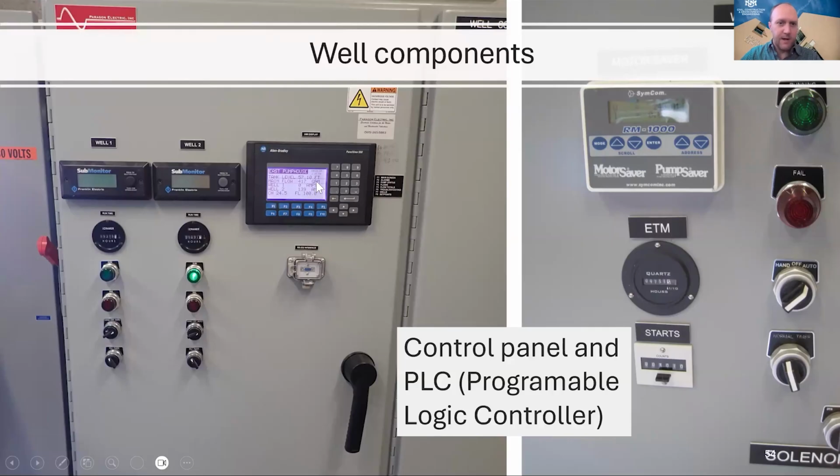by those pumps, how much flow there is at that moment. This is for two different wells. There's these sub monitors that monitor like voltage, and they're similar to this motor saver over here. So you can monitor how much electricity your pumps are using, and that can also give you some insight on if your pumps are starting to fail.